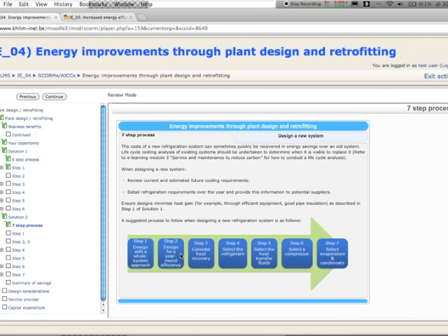You have to, because the outside temperature in winter is not the same as in summer, so you have to keep in mind that the outside temperature has an influence on the inside of your cold store. Consider heat recovery. Step 3 is, if you can use your heat again, you can recover it. It will greatly improve your efficiency. That's something you need to consider.